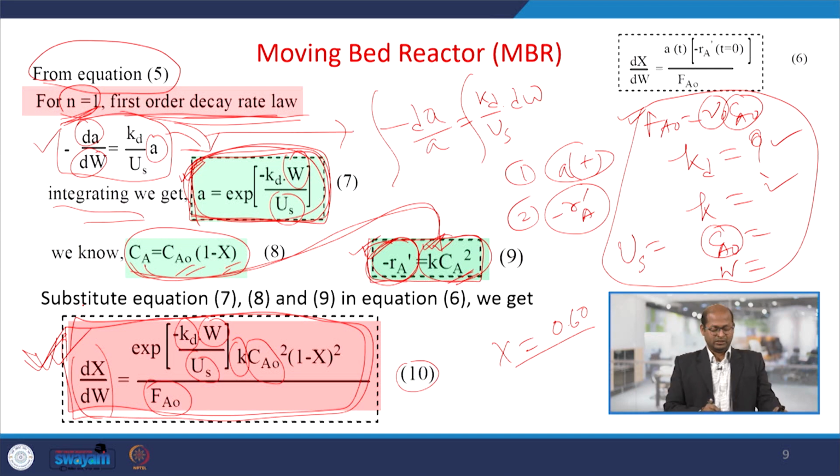Here we have not put in the pressure drop term, but you can include that term too and solve it as we did earlier by considering the Ergun equation. Here we are not considering it, there is no pressure drop in the system, so we only see how the conversion varies with the weight of the catalyst.